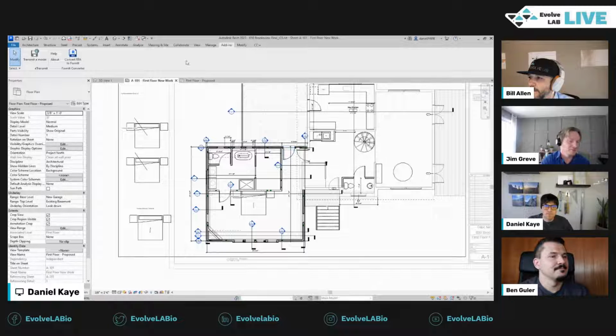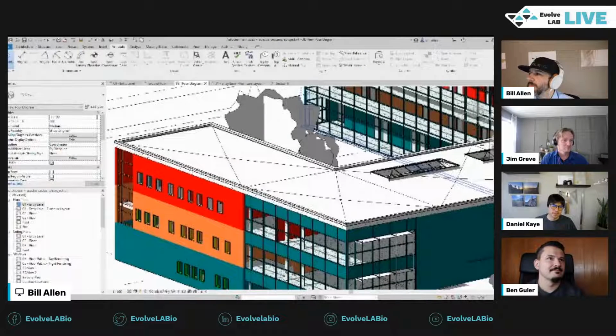Right. So if you're doing a pipe connector, you could model a cylindrical extrusion from the face of that object, and then have your connector on the end of that. Yeah, make a little pipe shape one for sure. One thing they didn't add, which would be nice, is visibility or optional connectors in families. You still need to make different family instances for different connector arrangements or positions. So maybe soon. Yep. I don't know, those are a few of the features I liked.